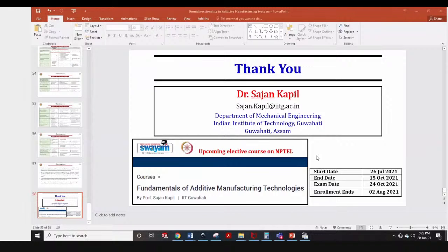And that is why, if you remember yesterday, off-axis nozzles were preferable in the case of laser cladding, right? Because they were just depositing in one direction and the cylinder kept on rotating. The direction was not changing. So if the direction is not changing, it is fine.